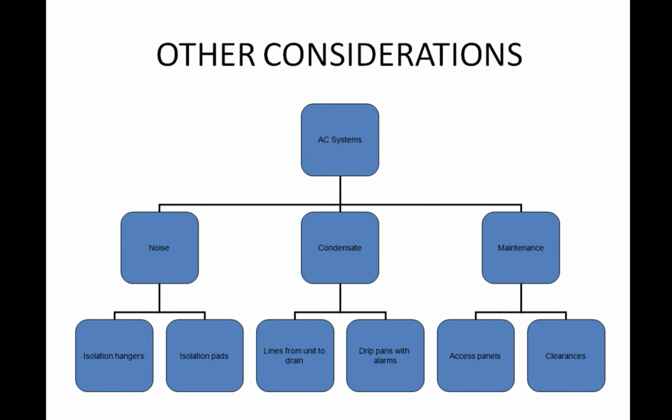Condensation is also something we worry about with an HVAC system. Obviously, where there's temperature differences, like when you're on a very cold bus or train or subway during the summer months. It's like the difference between being in a refrigerator and then stepping outside. It's 90 degrees. You get that condensation on the windows, and the same when it's 20 degrees outside and your house is nice and warm, and it's 70 degrees on the inside. You see that buildup of condensate. The same thing happens in the building system. It may not be as evident, but within that HVAC system, within the ductwork, there can be a buildup of water,